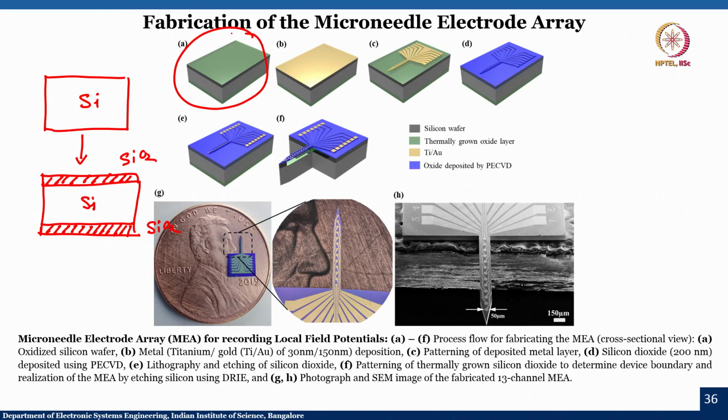Now, once you have this, you deposit your titanium and gold, because chrome is known to be toxic for implantable devices. That is why we go for titanium gold.